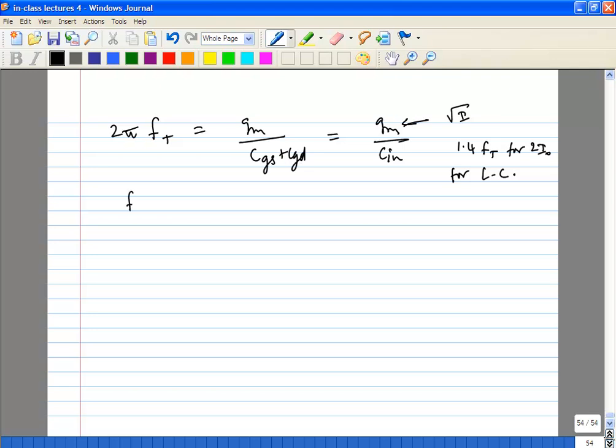So let's consider what are called FT doublers. Some very simple circuits to improve the overall FT response. The simplest FT doubler is actually your differential pair.